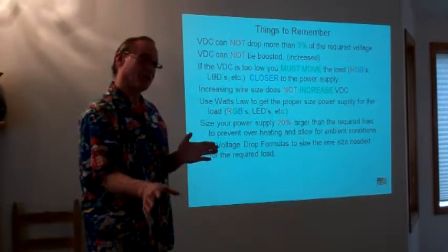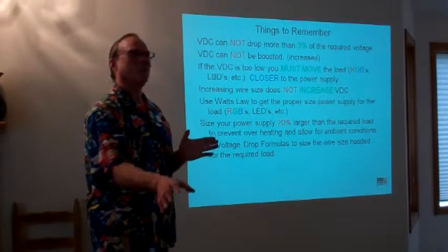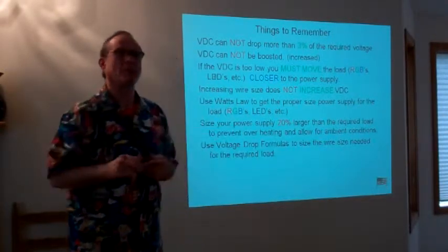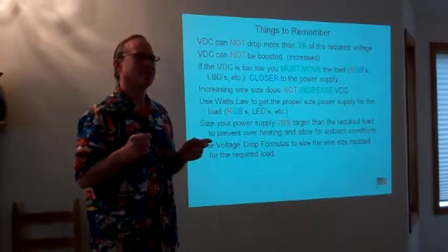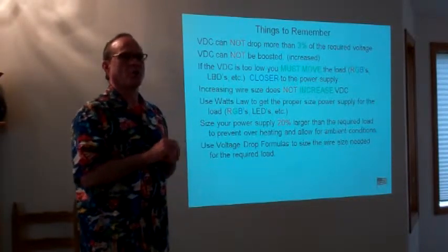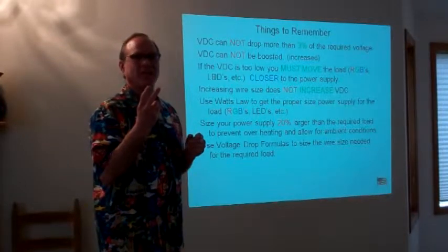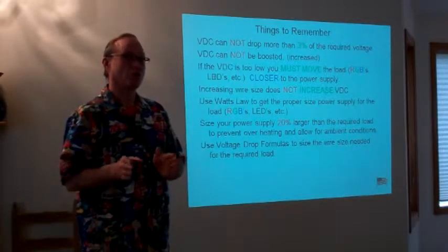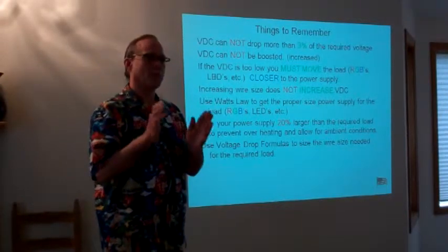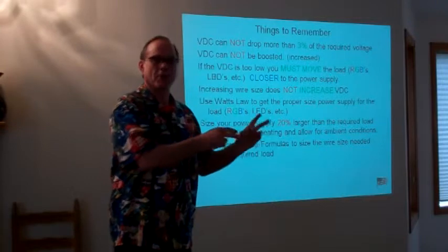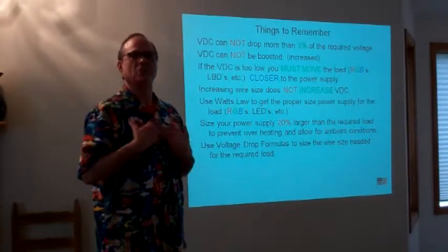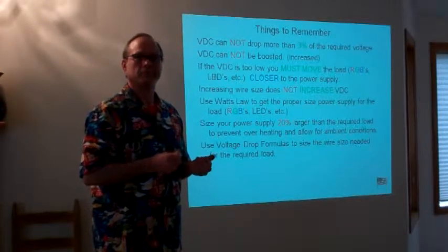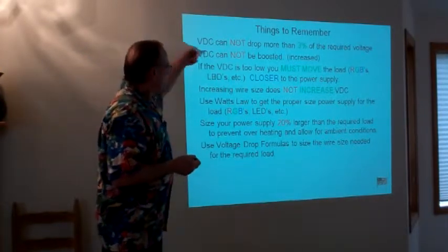But if I was to take this though, there's a caution. If I was to take that 14 volt supply and plug it onto the actual string, maybe you're going to do some bench testing, you're going to overvolt, you're going to overpower that thing by that 2 volts, and that's significant. If you're going to use these supplies and larger voltages, you can't apply that to the nominal 12 volt one. In my application we had 14 volts on the supply. You wouldn't want to put that on a 12 volt string. So we can't really increase it.